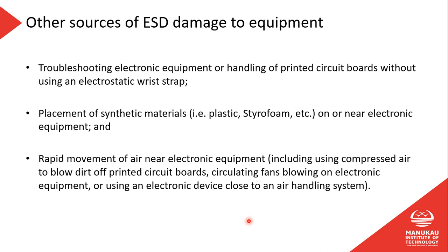Placement of synthetic materials on or near electronic equipment, so the potential for static to build up there is greater. Rapid movement of air near electronic equipment, including using compressed air to blow dirt off printed circuit boards, or circulating fans blowing on electronic equipment, or using an electronic device close to an air handling system. All of those things are very common.